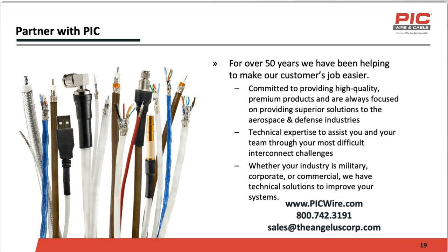Looks like this one is also for Mike, and here's the question. You mentioned it was repairable in the field. How is that possible? Yeah, that's another great question. It's really quite simple. First you just thread back the back shell, and then you can pull out the HSM by pressing the tabs together. The HSM will simply come out of the back shell.